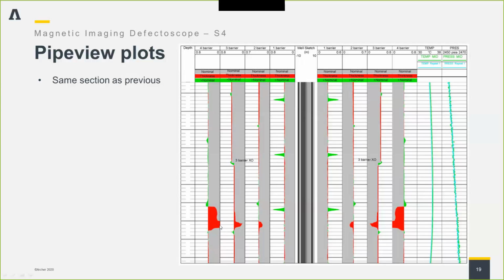There is definitely a hole through at this point, which makes it very likely that this may actually be a hole here, because we're getting corrosion at exactly the same depth on the string inside it. So this is an indication, in the way we look at the logs, that we've got serious corrosion on the outside, which is very likely to have caused enough corrosion for a hole on this one, and it's starting to come through here. This would be an indication that there is a problem with the envelope of the well.